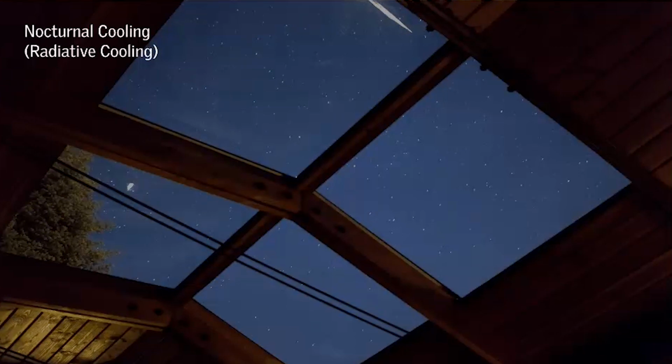So this also has an effect with skylights. If your skylights are not very thermally efficient, by cooling them, you could increase your risk of condensation at night. We talked already about that, but with regards to thermal comfort, if you're using low performance skylights, it can produce the sensation of a cool breeze coming off those